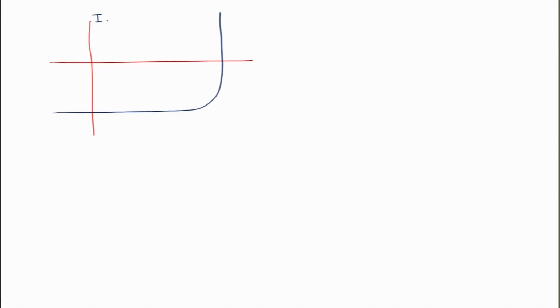So now when you plot this, you start getting a curve like this. So when you plot this, the I goes like this. So this is I, this is V. So this is at 0 potential, this is V is equal to 0. So you are going from 0 to a parameter called VOC. So at 0 bias, the current that we get is equal to ISC, which is called short circuit current, and up to some point the bias induced current is not large enough. As a result, ISC stays nearly constant.